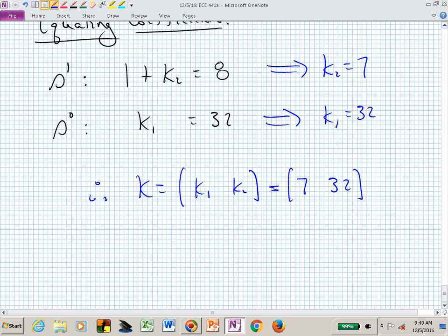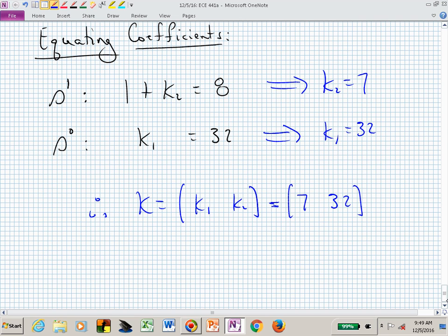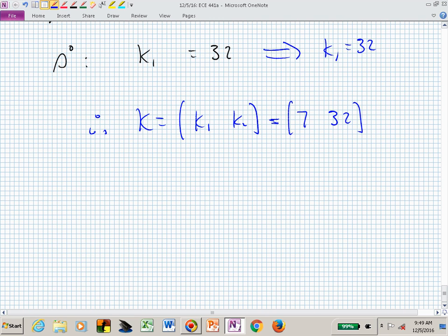And that's how we would weight. What's K1 waiting? It's waiting for the end of finals week? No, it's a different choice of the word weighting. Not W-A-I-T, but W-E, right? So this is now weighting what? The first component of the state vector, and K sub 2 is weighting the second state to give us what would be our closed loop eigenvalues in the F matrix. Minus 4 plus and minus j4 by design.